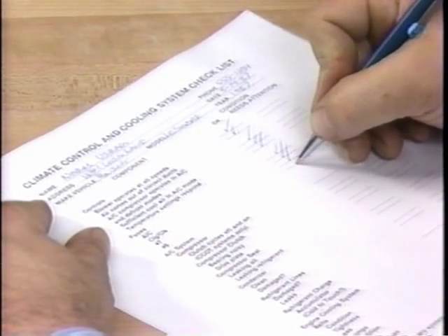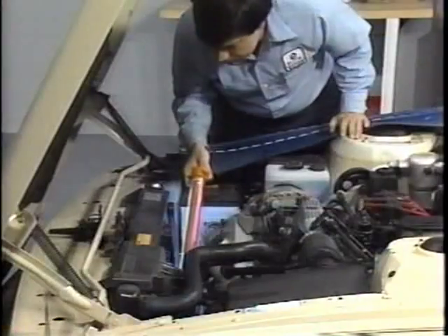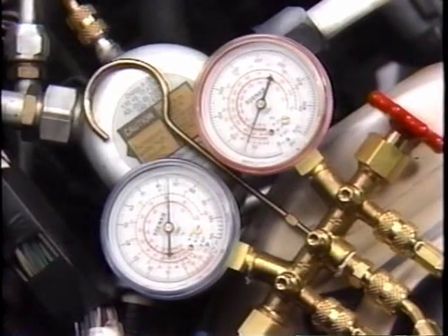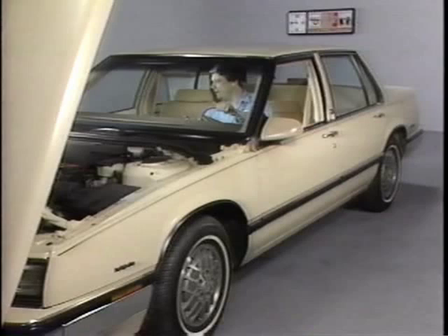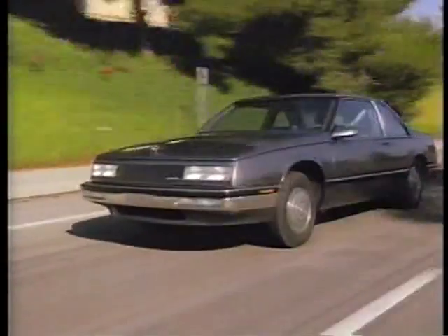But the important thing to remember is to use your diagnostic time to the best advantage. Begin with the easiest procedures, like function checks and visual inspections, which may reveal the cause of a problem. Proceed to performance testing and leak testing only when necessary. You'll find that many air conditioning problems can be corrected easily and quickly the first time. That way you can keep your customers cool and satisfied.